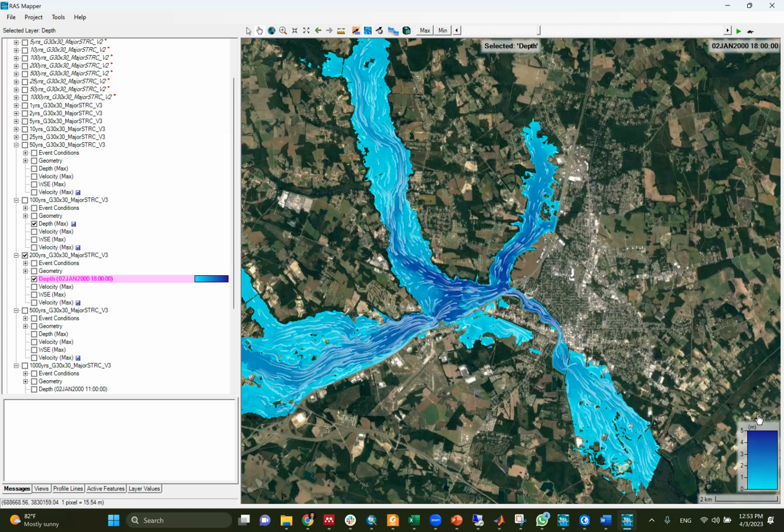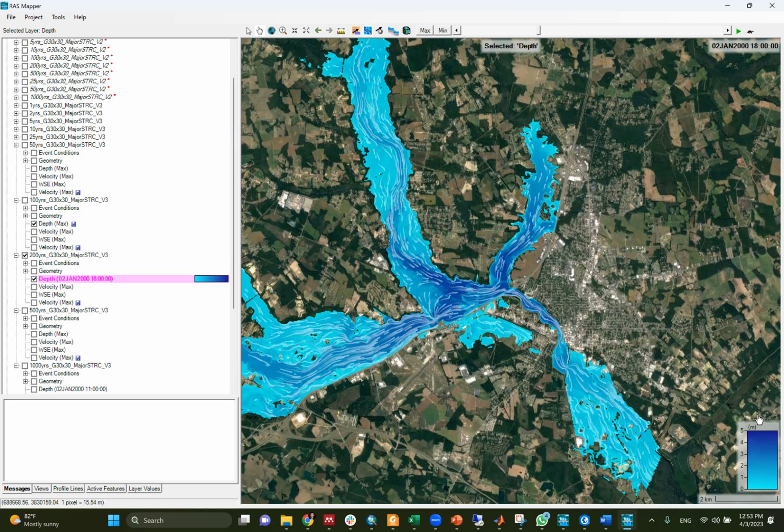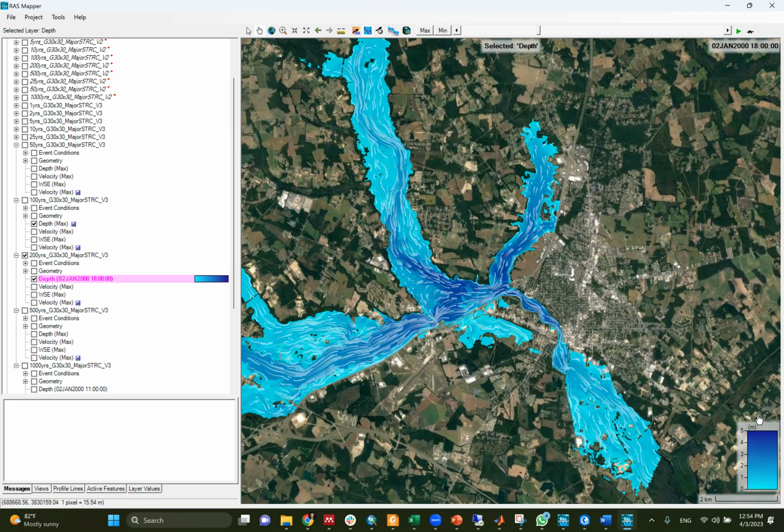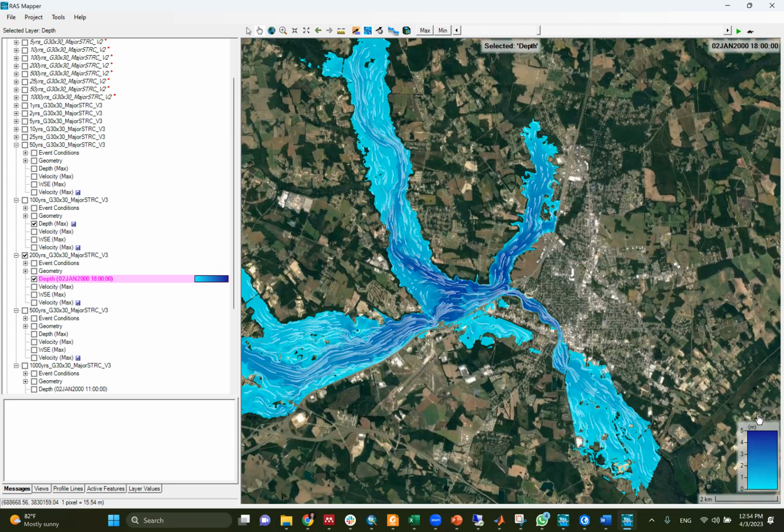But if you did enhancement to your building, what will happen? For example, if we are talking about wind, what if we used a hurricane clip between the roof and the walls? If you use 1, what if you use 2? What if, rather than 2 nails, you used 3 nails or 5 nails? If you use tile shingles or asphalt shingles, every one is changing completely different things. So you will have to redevelop the fragility.